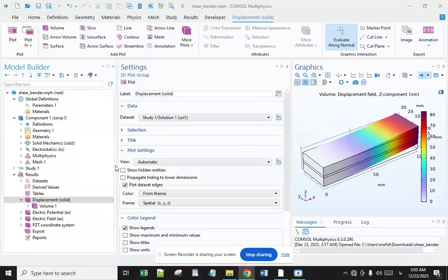This model is based on the use of mean and relative axial displacements of the midplanes of the faces instead of those of the upper and lower skins of the core used in the previous element. An extra shear strain due to the faces sliding against the core is then induced and all quantities are expressed in terms of the faces' displacements.